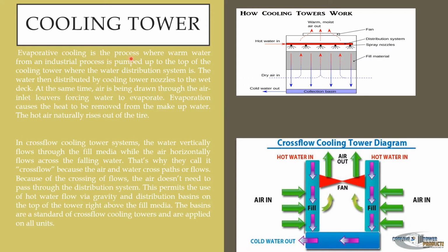Evaporative cooling is a process where warm water from an industrial process, heat exchangers, coolers and condensers is pumped to the top of the cooling tower where the water distribution system is done through nozzles. The water is then distributed by cooling tower nozzles to the wet deck. At the same time, air is being drawn through the air inlet louvers, forcing water to evaporate. Evaporation causes the heat to be removed from the makeup water. The hot air naturally rises out. This is the cooling tower working principle.